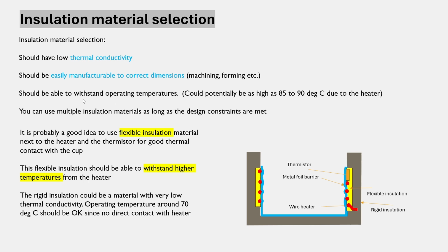And the third one is the ability to withstand operating temperatures. Okay, it shouldn't melt or catch on fire or something like that, but the chances of that is very little because most materials should be able to take the temperatures that we are going to see here. I don't expect it to go above 90 degrees C if you have everything controlled well. Only if you design really at the extreme, there is a chance that the thermistor doesn't see the water temperature, and the heater gets extremely hot.